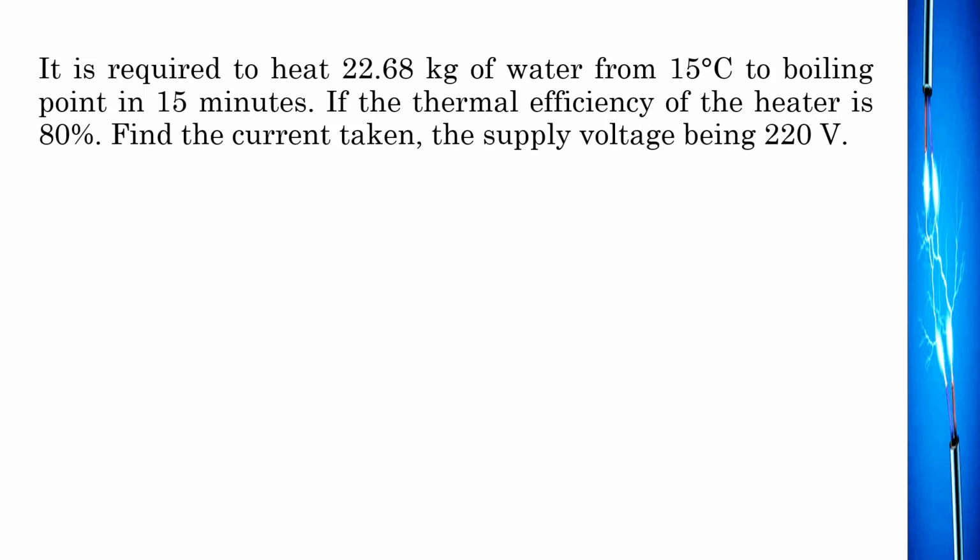Let's have this one. It is required to heat 22.68 kilograms of water from 15 degrees Celsius to boiling point. Tandaan, ang boiling point is 100 degrees Celsius. In 15 minutes, pagdating sa water yun. If the thermal efficiency of the heater is 80%, find the current taken if the supply voltage is 220 volts.